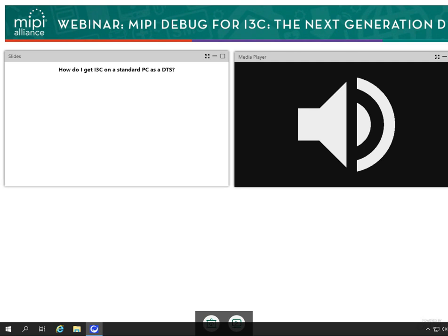Okay, very good. Is there any relationship between I3C and I2C? Yes, I3C was developed to be backwards compatible to some degree. We talked earlier about I2C slave or target devices, and the standard communication in what's called single data rate, or SDR, mode for I3C is very much based on the standard transfers in I2C.